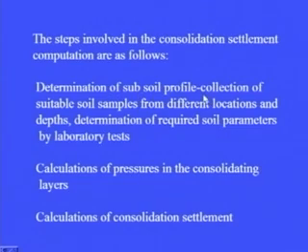The steps involved in the consolidation settlement computations are as follows. First of all, we determine the subsoil profile, and in order to determine the subsoil profile, collection of suitable soil samples from different locations and depths, determination of required soil parameters by laboratory test, then calculation of pressures in the consolidating layers, then the calculation of consolidation settlement.